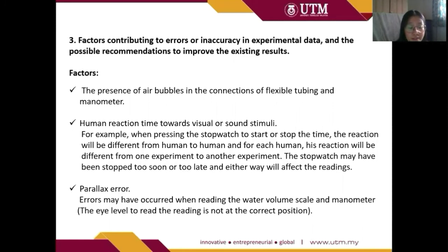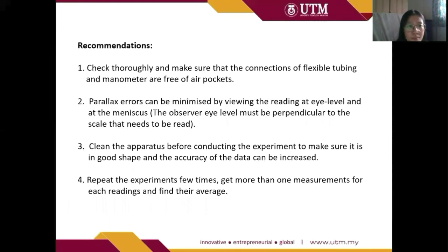And next is the parallax error. The error may occur when reading the water volume scale and manometer, which means that the eye level to read the reading is not at the correct position.